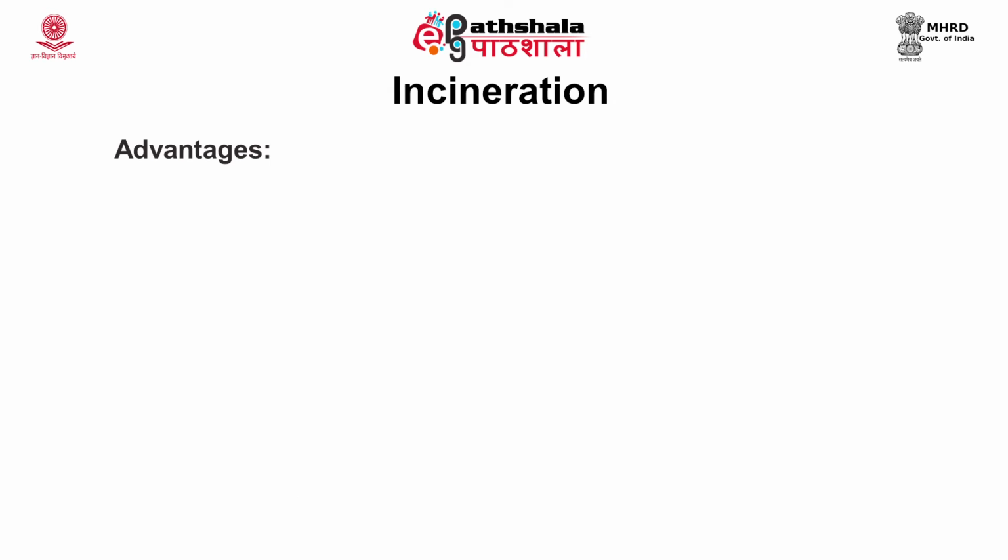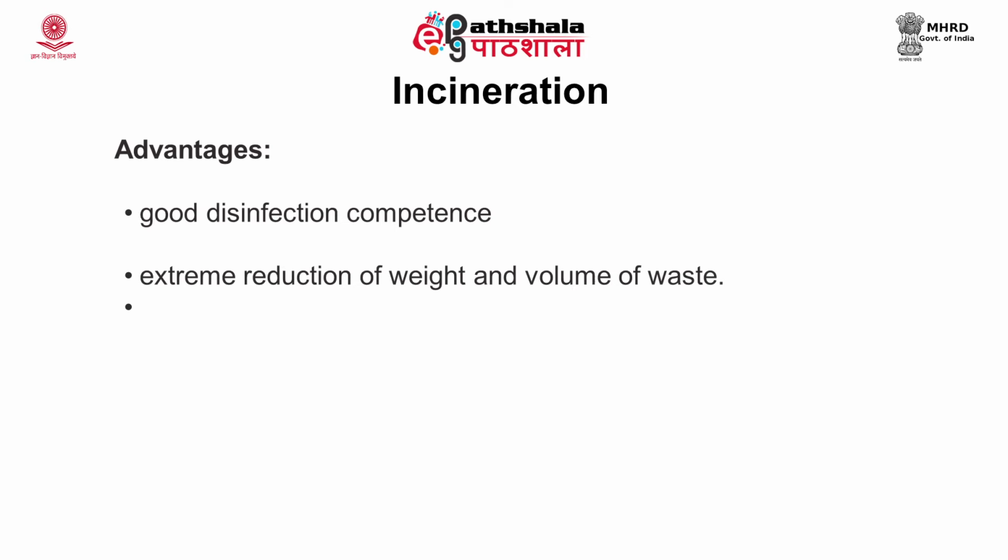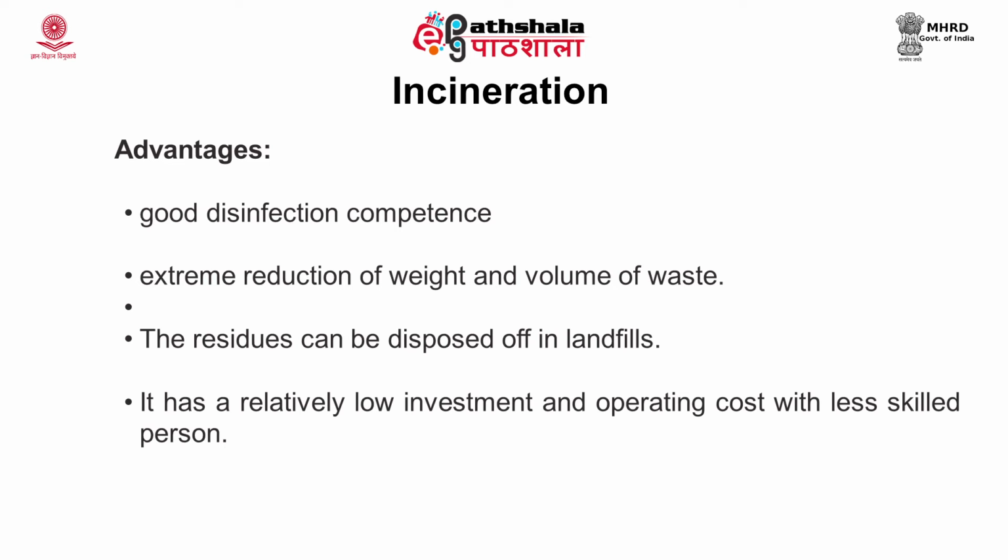Now, the advantages of incineration: it provides good disinfection competence. It results in extreme reduction of weight and volume of waste. The residue left after incineration can be disposed of in a landfill. It has relatively low investment and operating cost, with less skilled personnel.